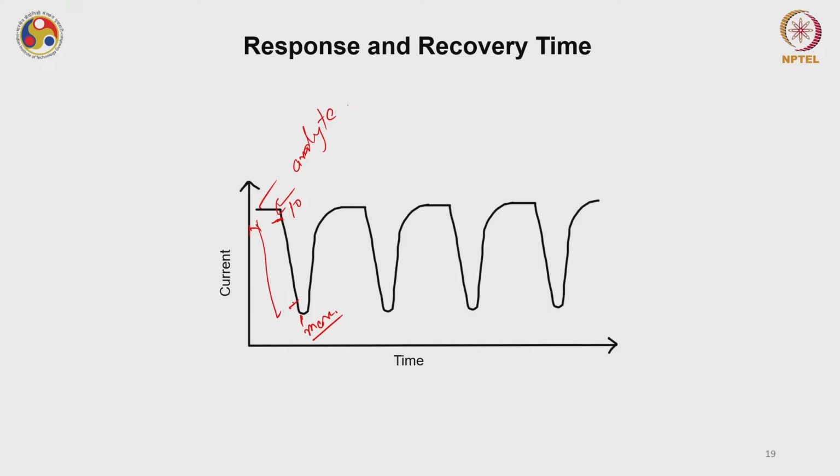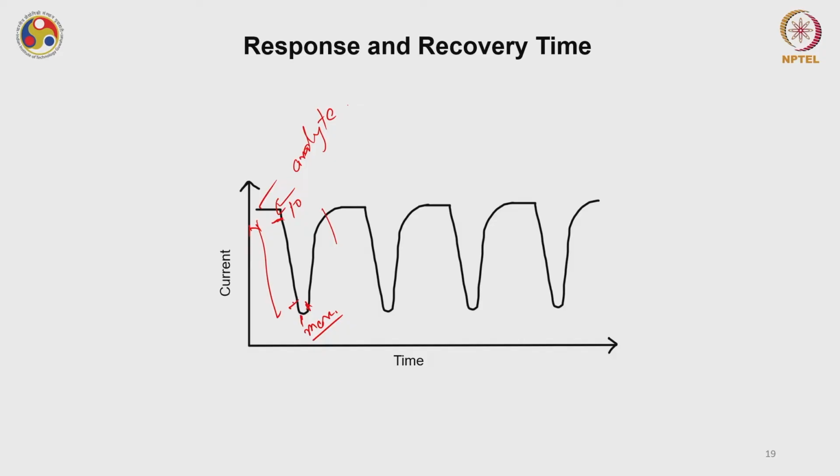Similarly, the same concept is applied for recovery time. So it is the time taken from 90% of the maximum value to 10% of the baseline value. This definition has been under debate. However, till now we are using this definition. This is very crucial, particularly for sensors which don't saturate.